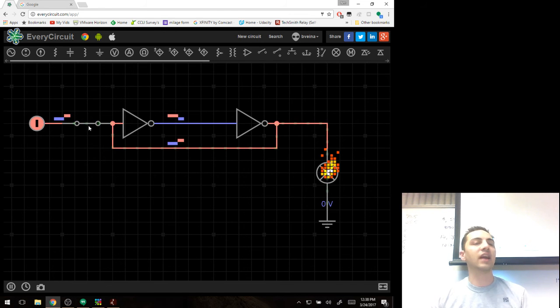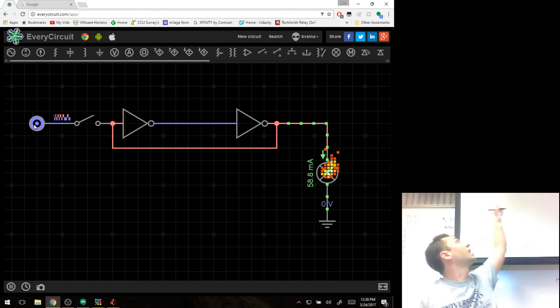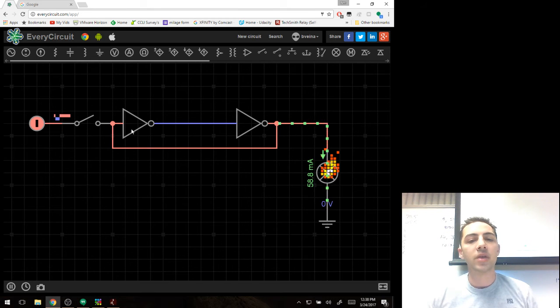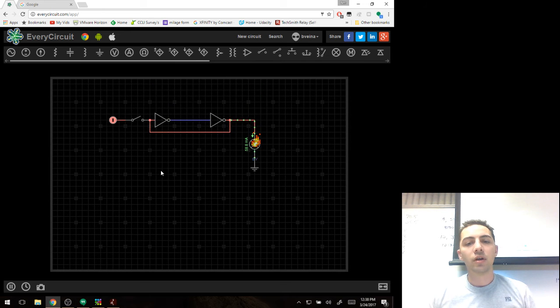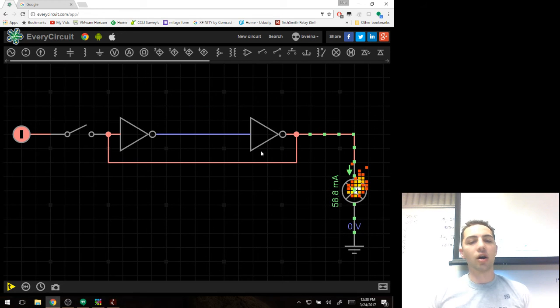So you set it, and then when you stop providing input, I don't mean you provide a 0 input, I mean no input. It's completely disconnected. I can twiddle this now, and notice there's no change in the light. Can you see that it's showing me when things are transitioning high and low? Okay, good. So that's my first demo to you. 2 inverters are a way to provide memory.